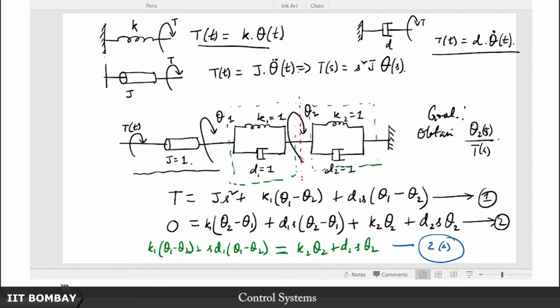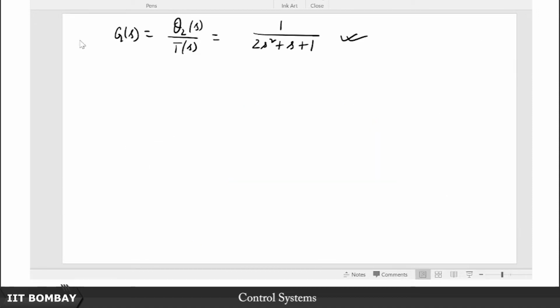And if you recall from our previous lecture, we've already seen how to reduce these blocks. You see, if you treat these terms like impedances or admittances, when they are in parallel, you can simply add them, because we've seen that the parallel equivalent is closer to the physical reality. So these are then like admittances. So you can add these two, and when they're in series, then you get to add their reciprocals and you get the equivalent reciprocal. So let us try and do that. So what about the first block here? Let's just look at this one. So I'm now just going to replace it by its transformed equivalent.